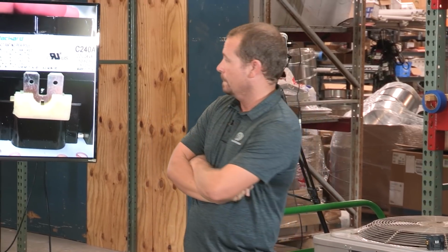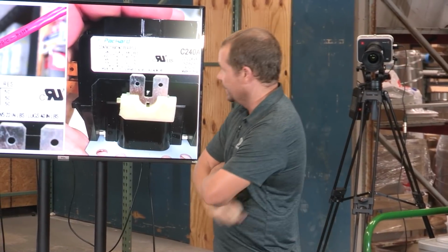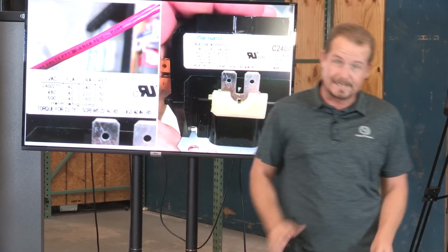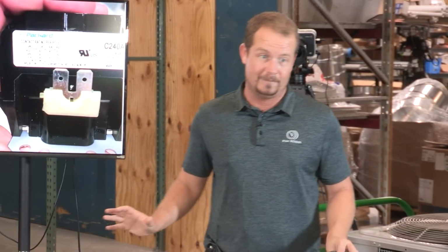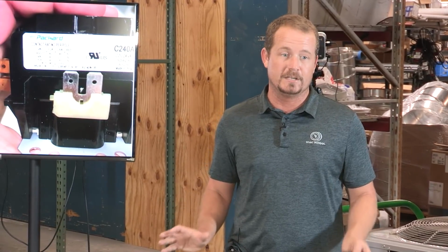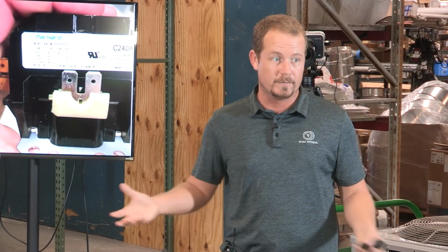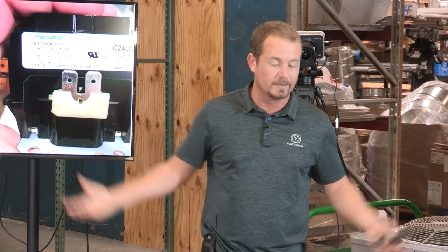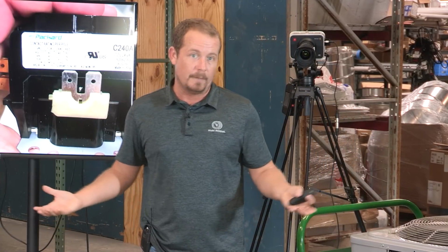75, right? So if you wanted to make it higher, you'd have to make sure that everything down the line, your disconnect, your breaker, everything was rated at 90. But sometimes that may be the thing to do. Sometimes if the option is between changing all your termination points to something that can handle it or rerunning an entirely new circuit, that may be the thing to do.